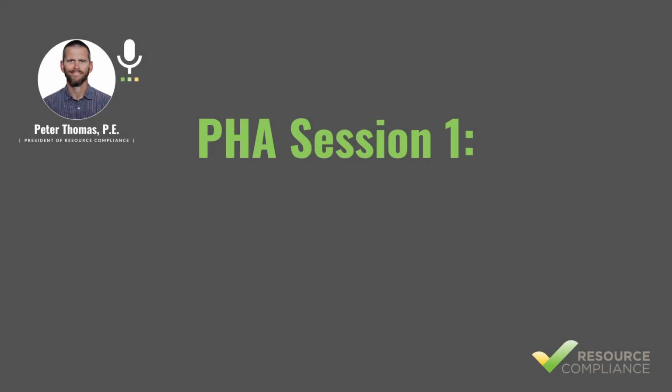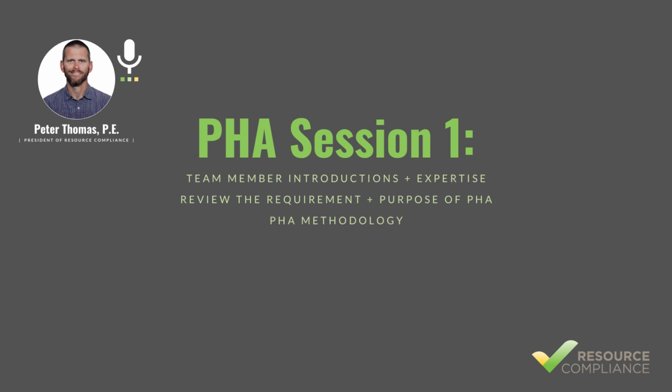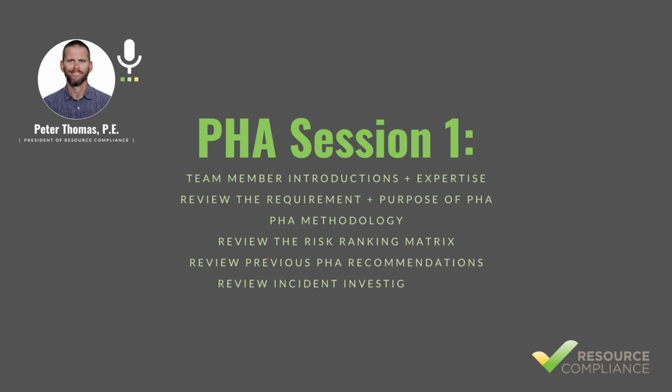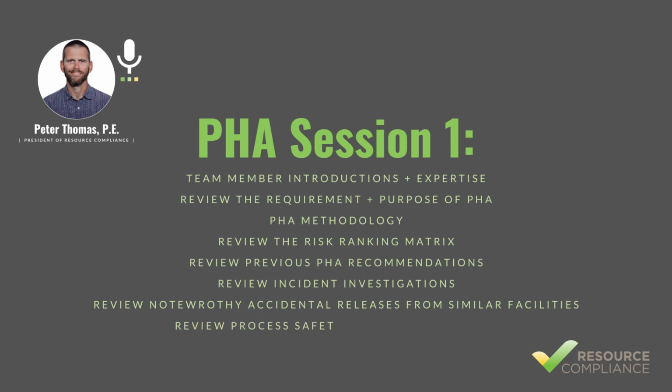It is a common practice of Resource Compliance to conduct the PHA in multiple sessions. The number and duration of the sessions will be determined by team member availability and system complexity. The first PHA session is typically used to introduce each member of the PHA team, review the requirements and purpose of the PHA, introduce the team to the PHA methodology that will be used, review the risk ranking matrix that will be used to assess risk, review any previous PHA recommendations that have not been resolved, review all incident investigations that have occurred since the last PHA was performed, review noteworthy accidental releases from similar facilities, and review important process safety information such as P&IDs.